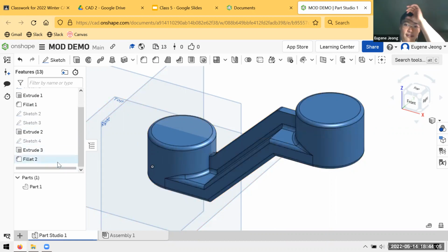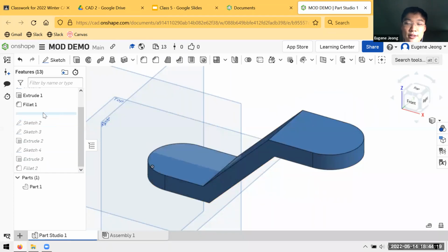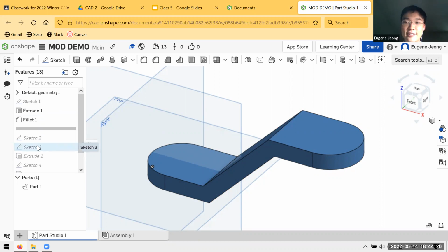And now you might be thinking, why is that useful? For one thing, if you're editing things, a lot of the time you want to keep your document well organized, right? I like to stress a lot that you want your models to make sense to other people who look at it. So sometimes that comes from things like we've talked about before, like construction geometry, where you want all your lines that aren't part of your boundaries to be construction lines.